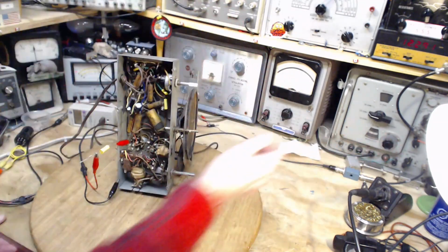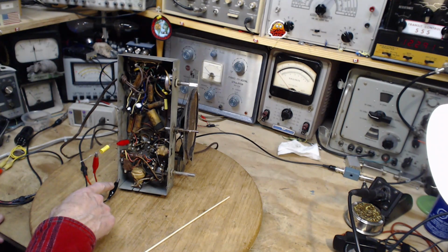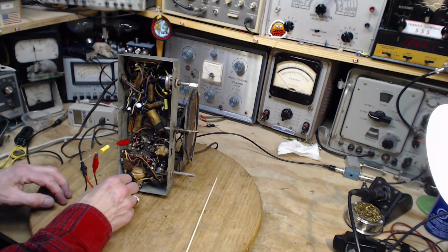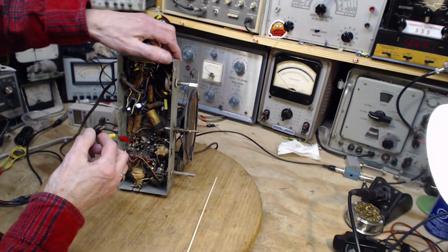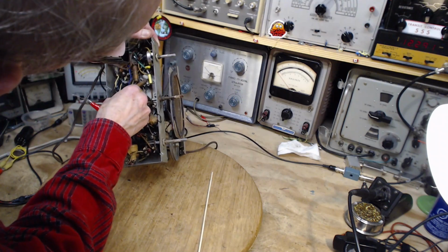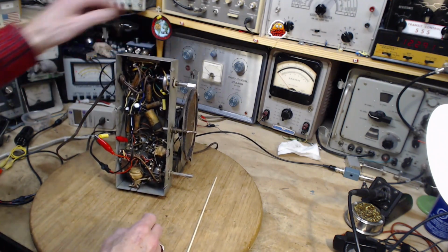So it's there, but it's got a hum interference, and I'm sure it's from this connecting to the chassis here rather than the B-. So if I didn't want to connect to the B-, yeah, let's do that, but I'm going to turn the radio off while I do it. That should be a little better. Back on.